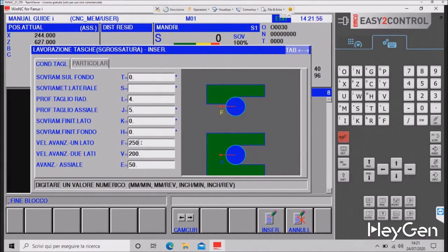It automatically sets it the same for me. And you see, I made a mistake. It's not adjustable, so the actual feed rate remains the same. This is a small limitation of the manual guide. Obviously with ISO, we wouldn't have this problem. Now, regarding the entry feed rate when the cutter enters from solid, the manual guide allows me to modify that. It's obviously more important because when I enter from solid, I need to lower the parameters a bit.